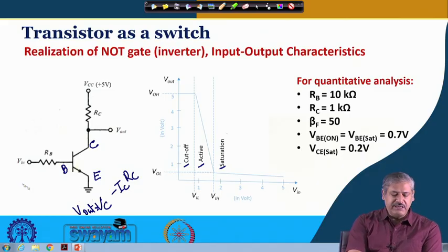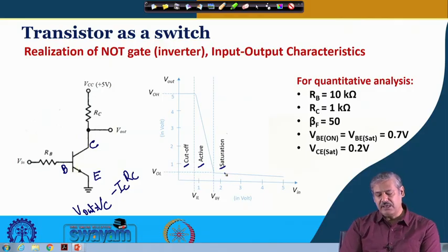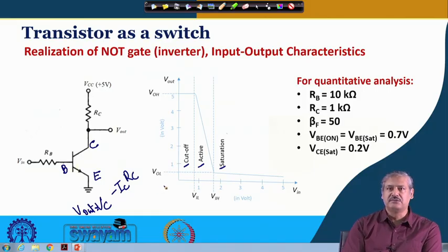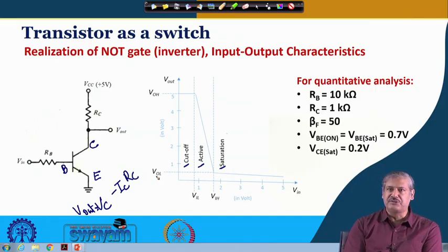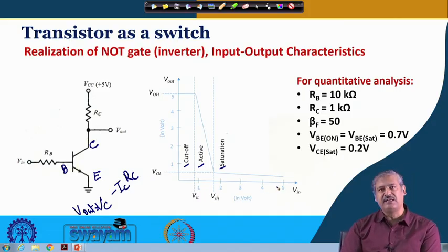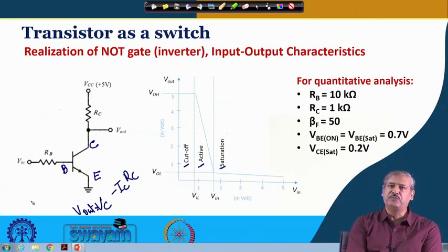After that, any increase in the voltage Vin, the transistor remains in saturation. Before that, it comes out of saturation. Is it clear? We call that particular voltage VIH. What happens at that voltage? At that voltage we know firmly that the output is in saturation and the voltage here is about 0.2, 0.1 volt or so, which is considered low at the output level. So any voltage higher than that at the input side will necessarily make the output low.